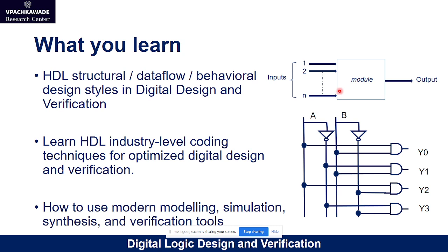When you use a particular HDL, which is hardware description language, you will learn the different coding styles, behavioral or structural. For example, at the top is the behavioral modeling style. It means inside this black box, you don't know what the logic is. You basically have only the inputs and you define the outputs. And automatically the logic gets built based on your coding.